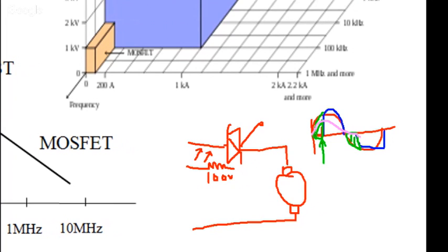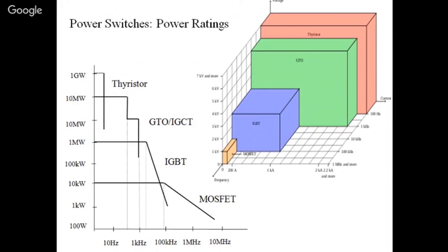The average AC will be a value like this, which is a lesser voltage compared to the original voltage coming. So this is what the power Triac is doing. It is just clipping some portion. Okay, you're just firing the device. So all these devices, if it is a Triac or a Thyristor, it acts just like a switch. So what is the difference between the ordinary switch we use here and this power switch?